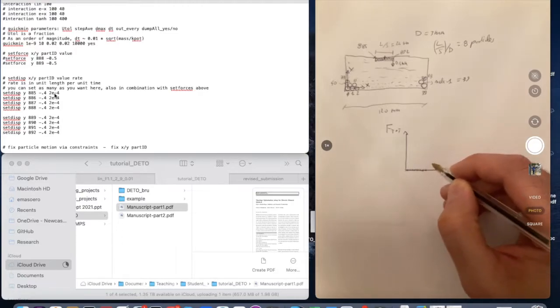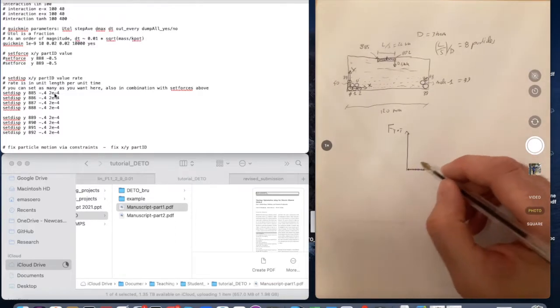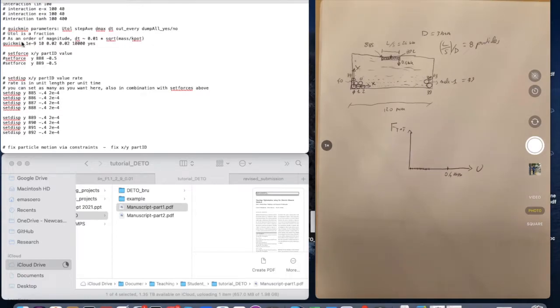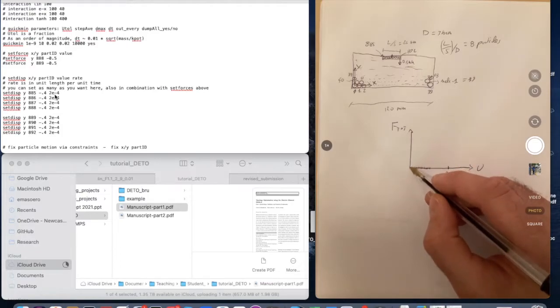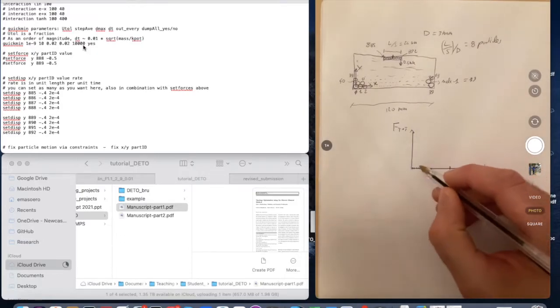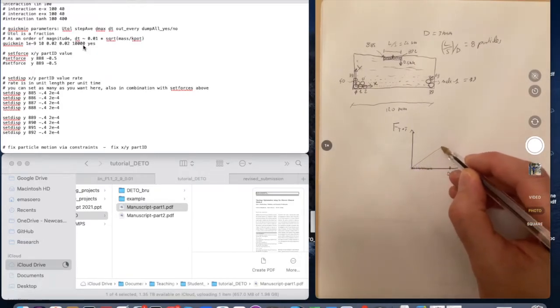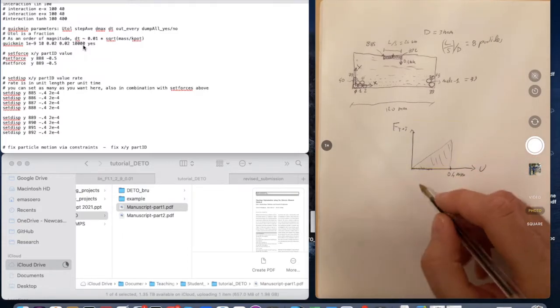So what it's doing is essentially a dynamic simulation, but it is highly damped. So it's a quasi-static simulation. This simulation is the quick min that we were running before, with this time increment of 0.02 seconds. But then we have to tell the code how fast we want this imposed u to increase during the time of this simulation. So at which rate do we want to increment u to obtain the force displacement curve here, and then eventually the energy under it. And this is the rate.